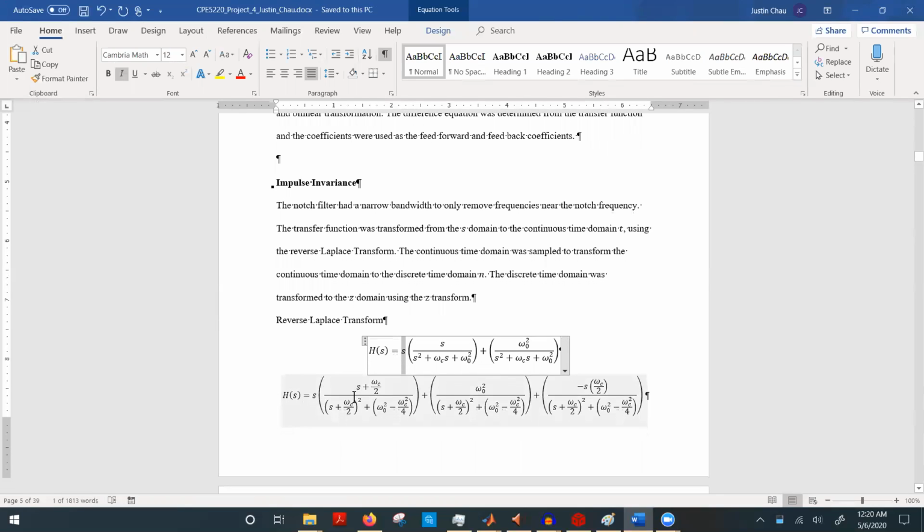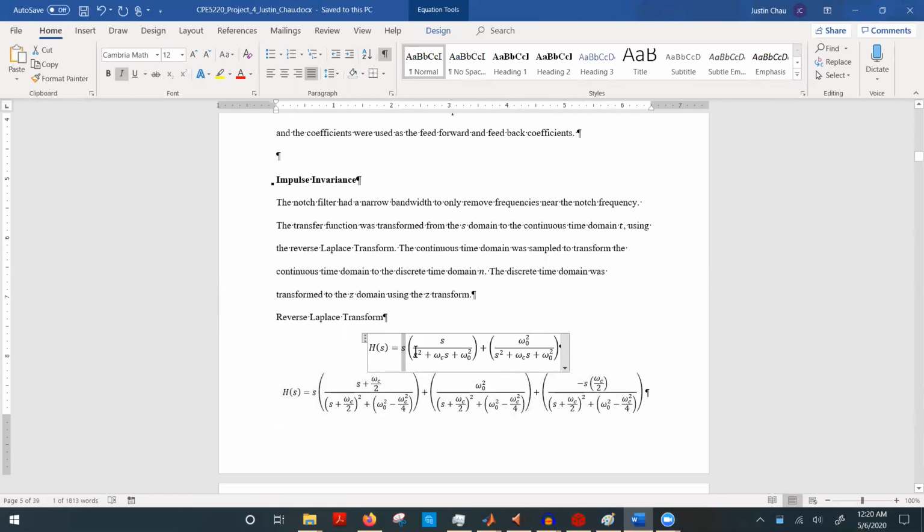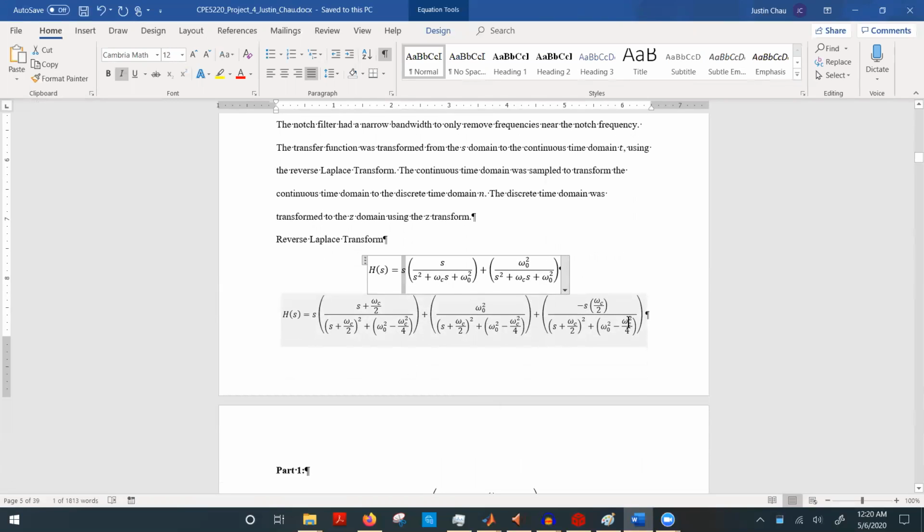but we'll get to that later. So I have this, but now I also want to complete the square. In order to complete the square properly, I set this up, but with this S plus another value, I want to match that in my numerator. But if I'm going to add an S times omega C over 2, I have to subtract 1 as well to keep everything balanced. And this value has remained the same. So with this, I have essentially three parts, and I now need to perform the inverse Laplace transform on all three of these parts to get the time response.